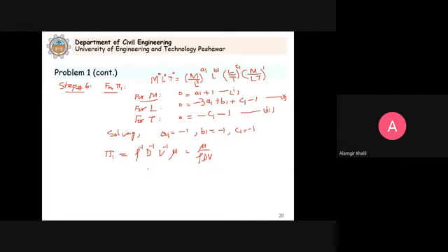Now we identify that this rho V d and this mu make something familiar, because we already know that rho V d by mu is actually a Reynolds number. You see, this is how dimensional analysis helps us identify which number is important for that problem.